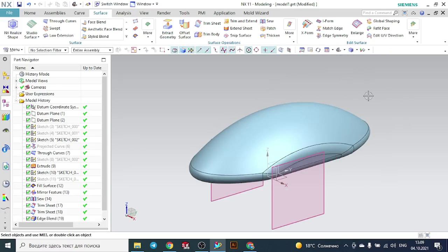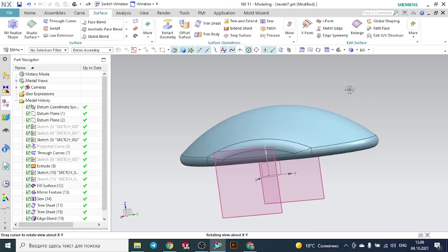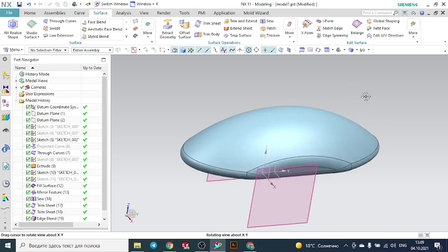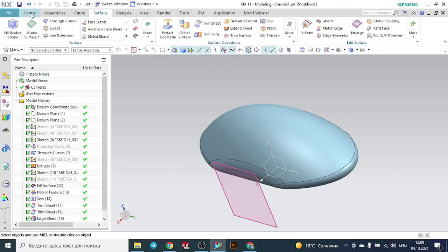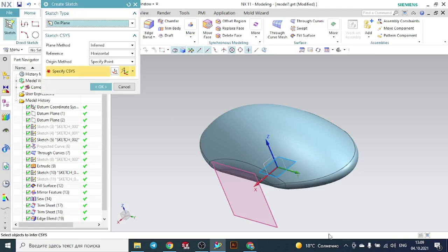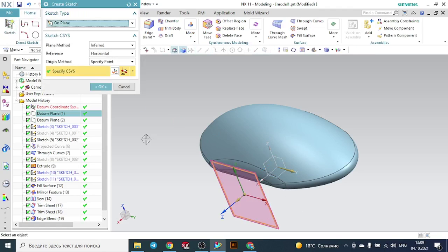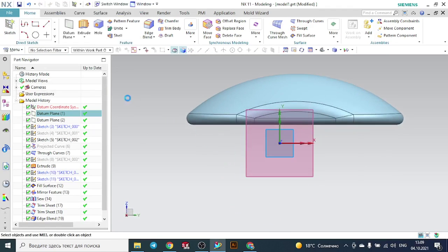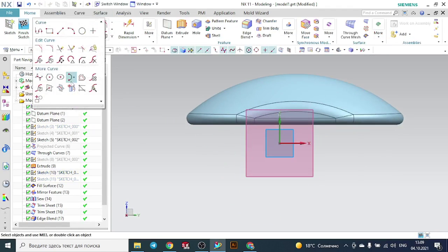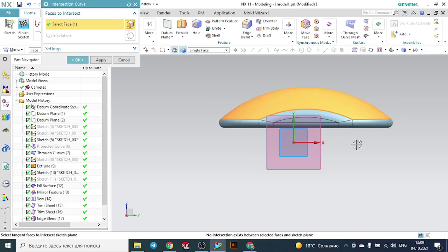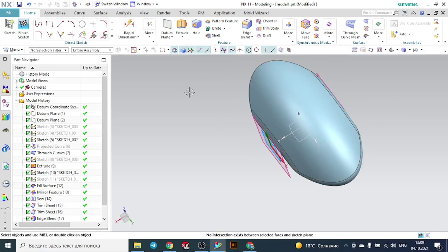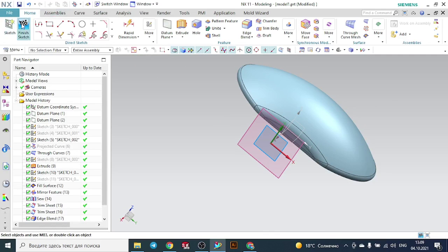So this is our element. Now we will draw one more feature for this system. In order to do this, let's go to Home, select Sketch, and select this face, press OK, and select the intersection curve here, which we have seen. Select the single curve and select this face. Now let me finish.